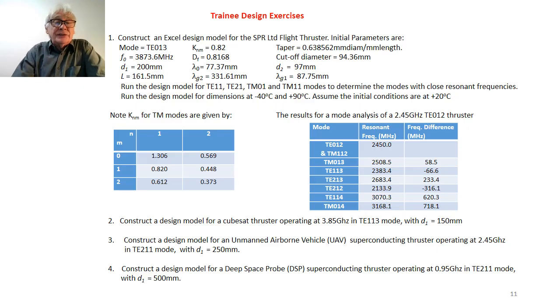I would suggest that you run your design model for TE11, TE21, TM01 and TM11 modes, and just see what resonant frequencies you come up with. And you can then decide yourself whether these are going to cause you problems or not.